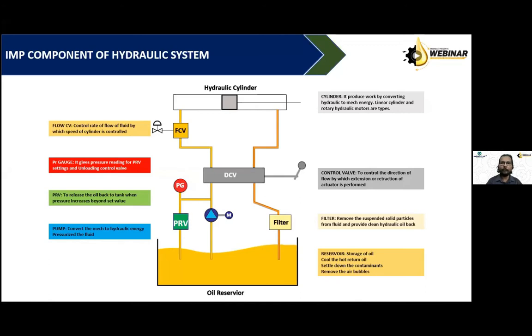So any contamination, solid contamination, or moisture, or we can say water contamination, both damage the fine clearances and mating surfaces badly, and deteriorate the performance of the pump very quickly.